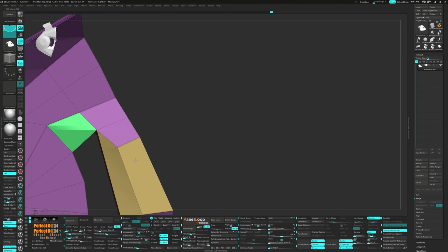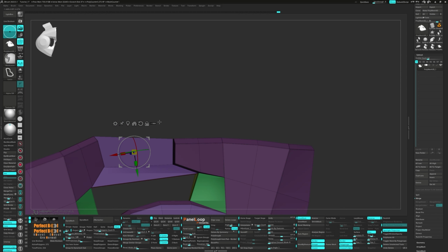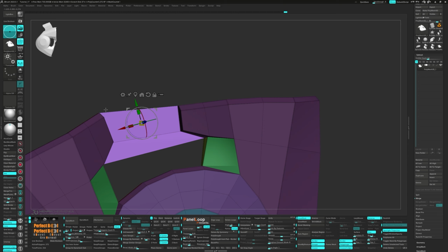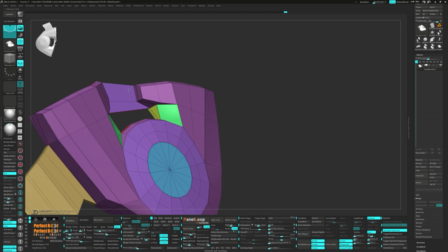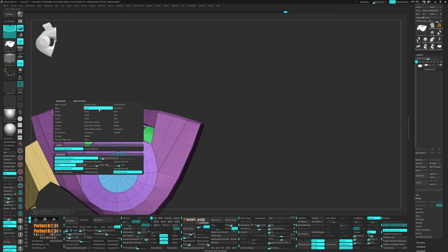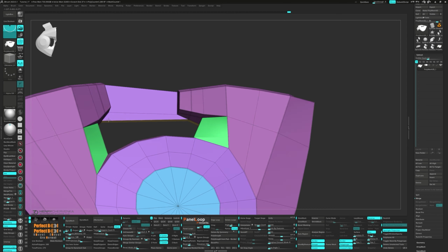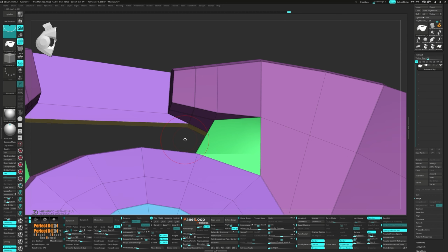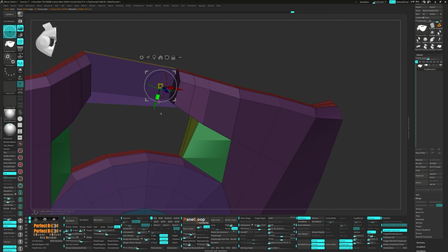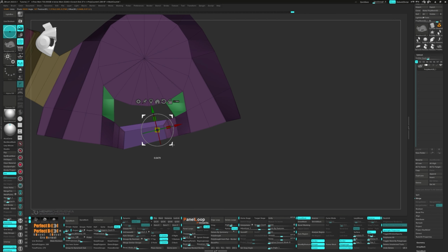Then there's double mode. When on, it makes panels with both front and back surfaces. When you turn double off, you get panels created as bevel sections on the original surface. Next up is the append setting. When you turn this on, ZBrush doesn't get rid of the original polygroup when panel loops is made. Then you've got inner mode. This makes panel loops inside the model instead of outside. Next is thickness, which sets the thickness of the panel and affects the distance between the panels.